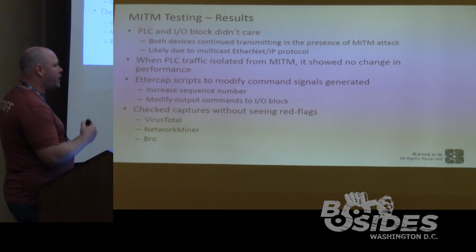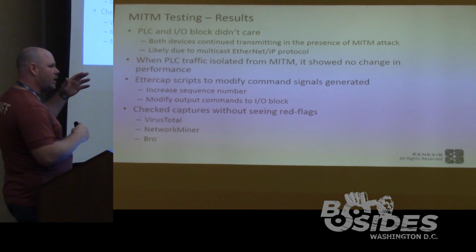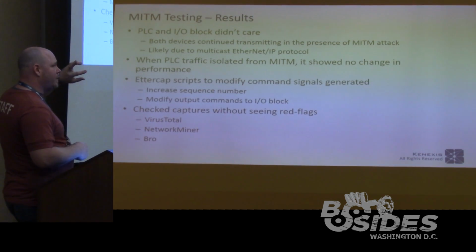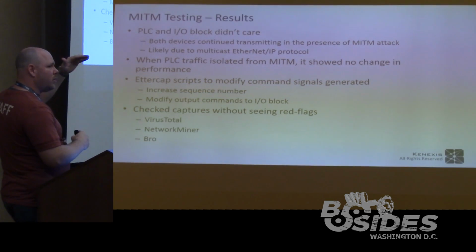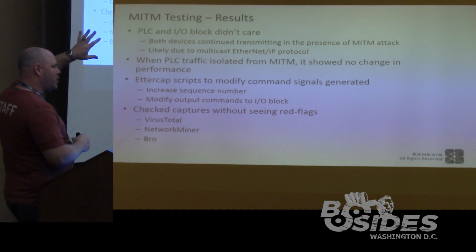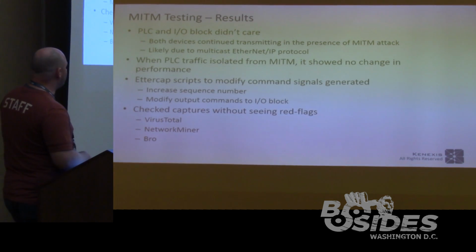There's a sequence number in the traffic stream to identify the packets, so that if you get one that's out of order, because it's multicast, it's not using TCP, it's using UDP. So again, you don't have that session information to make sure your session comes in the right order. So that's handled by the industrial protocol, and the industrial protocol can be spoofed by just advancing the sequence number out of range. So you can get it to basically forget about what's going on.